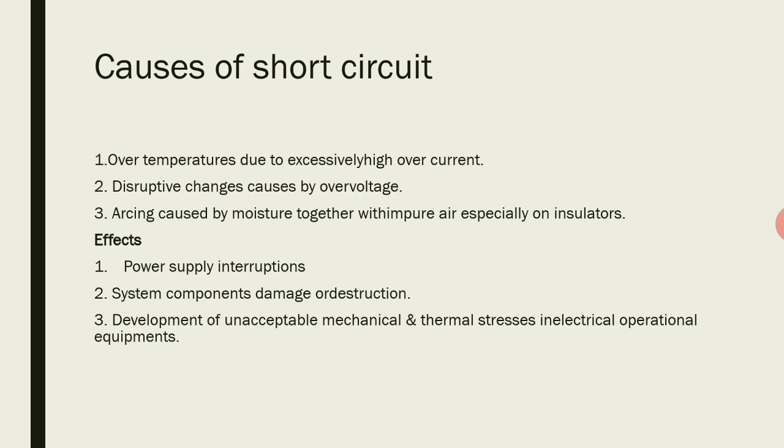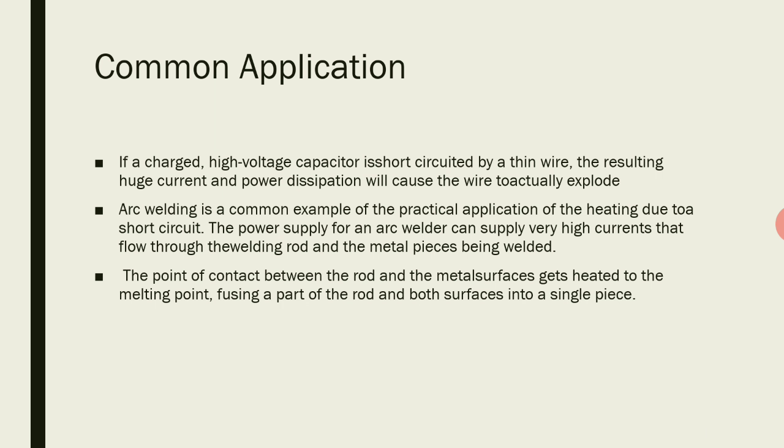Now let's see some of the causes and effects of the short circuit. Causes: over temperatures due to excessively high overcurrent, disruptive changes caused by overvoltage. Effects: power supply interruptions, system components damage or destruction, development of unacceptable mechanical and thermal stresses in electrical operational equipments.